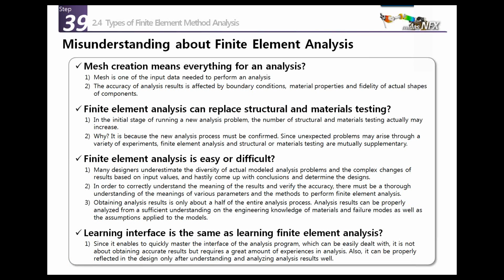So of course, mesh is one of the input data, and it's required to perform the analysis, but the accuracy of the result is affected also by the boundary condition, the material properties, the fidelity of the actual shape and the components. The mesh creation is important and the quality is important, but it's not everything. It's only one part of what will give you the accuracy of the results.